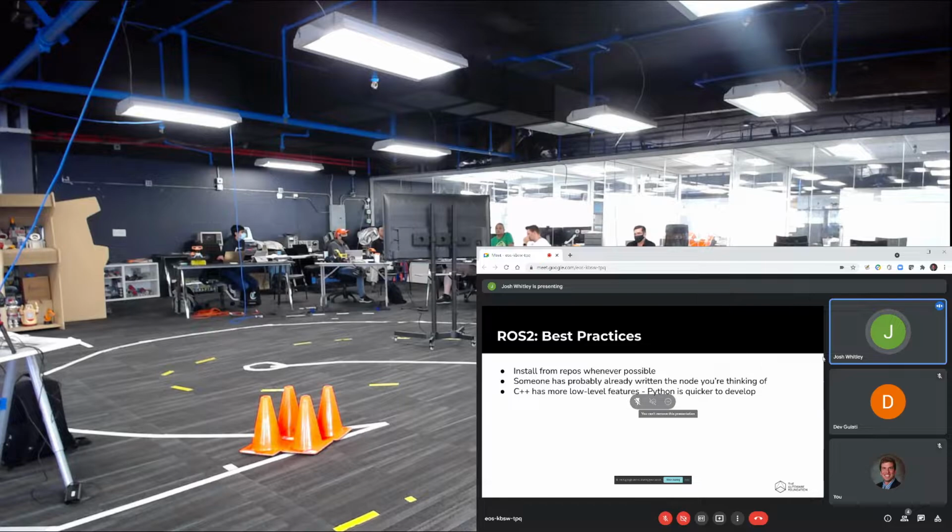And when you build that package, it builds C++ headers, it builds Python objects, it builds Rust objects, it builds C# objects, and it just does that automatically when the package gets built. So all of those languages have access to some representation of that message. So when they publish to DDS, DDS doesn't care that it came from a C++ node or a Python node. It just knows this is the data, this is the message structure. Pass it on to whoever's listening.